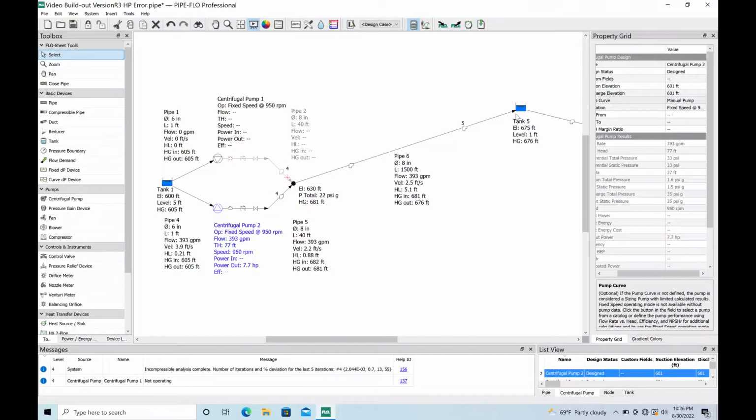And it discharges up here to this high point. We're calling this an air release. There's some gravity pipe downstream of here that's of greater capacity, so we're ignoring it for the calculation, but 393 at 77 feet of head is what you want to remember.